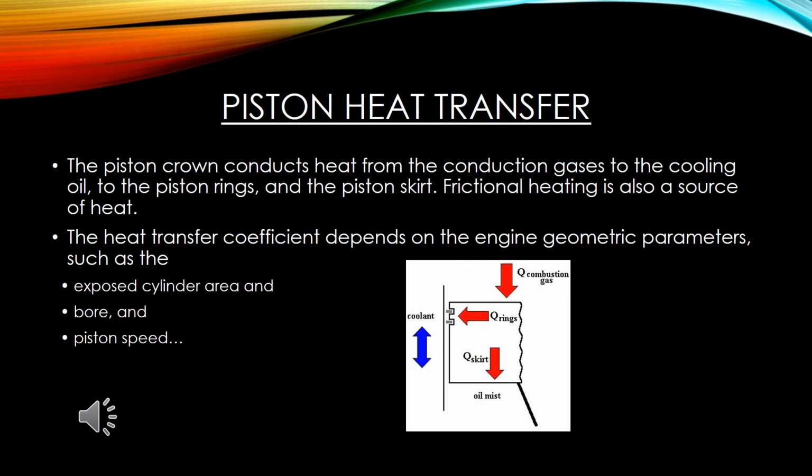And then piston heat transfer. The piston crown conducts heat from the combustion gases to the cooling oil, the piston rings and the piston skirt. Frictional heating is also a source of heat. The heat transfer coefficient depends on the engine geometric parameters such as the exposed cylinder area, bore and piston speed.